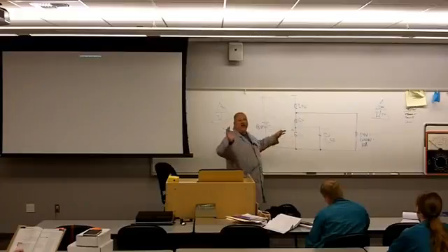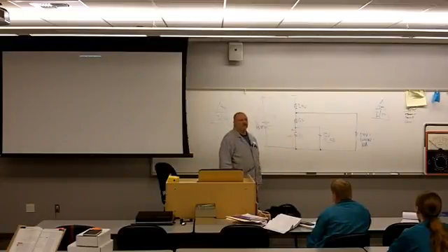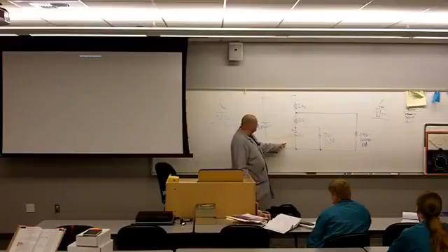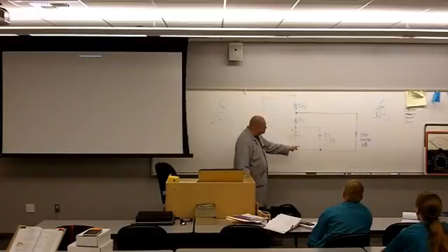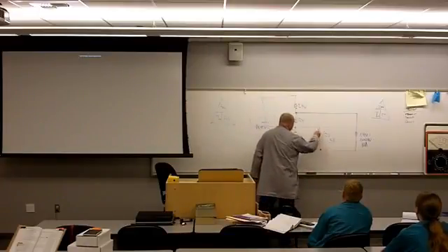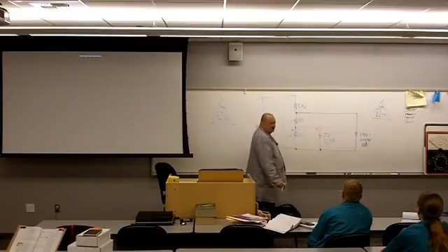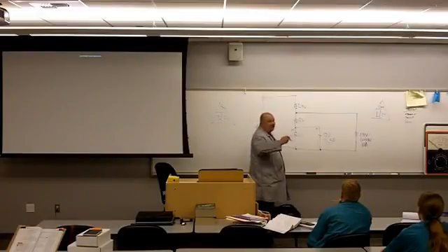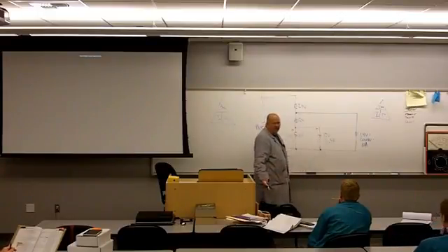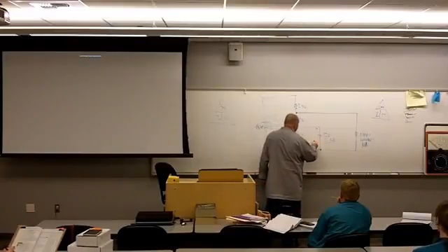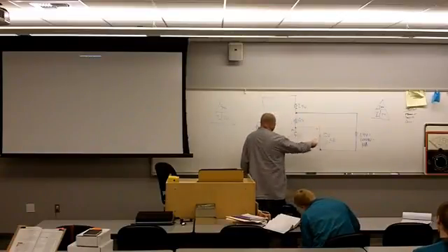So right there, we just unlocked the entire circuit, because what we've got here is 1.05 amps coming up out of this node. How much current do we have coming up through here? 0.5. Where did that number come from? The paperwork. Thank you, the paperwork. Or your calculation, if the paperwork left out the current demand, you know it's a 5-watt radio, and as long as you can prove it to somebody. So we called that 0.5. So we've got 0.5 amps coming up through here.